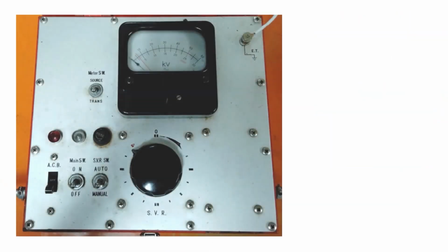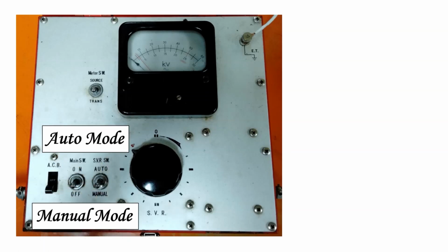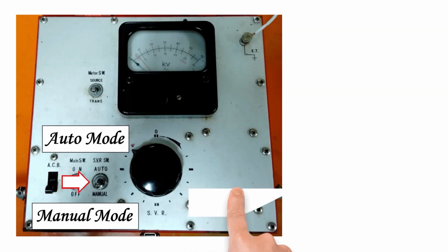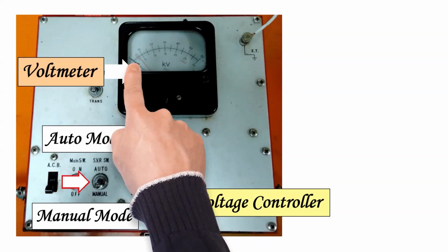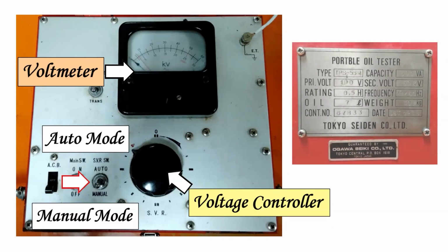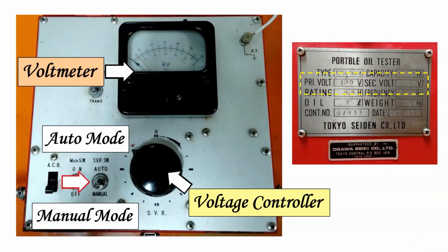This portable oil tester can be operated in two modes, auto mode and manual mode. So the required mode can be switched using this third switch. Also, there's a voltage controller along with a voltmeter in the kilovolt range. In addition to that, this equipment has the main transformer united with the control portion, and it is used to step up the input voltage of 100 volts to 50 kilovolts.